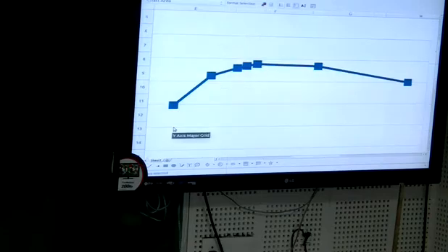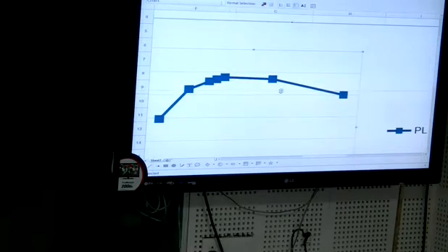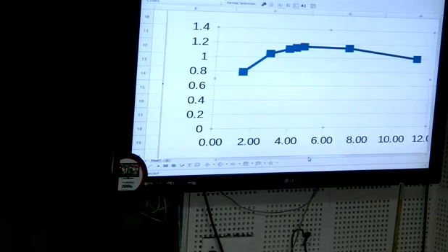So I'm getting something like this. X-axis is the resistance. And reduce the size of this. X-axis is the resistance value and Y-axis is the power value. So at one particular value of this one, it is maximum. Okay. So that's about measurement. So let's quickly derive also, just to say that when the value is equal to RTH, it is maximum. Okay.